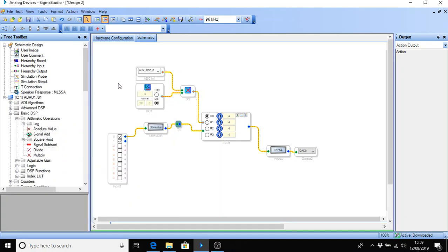So there we are. That's the end of this video on programming filters. There are other methods of selection, as I said. Instead, you can use a binary input on here by having 4 of these and using these as general purpose input pins. There's loads of examples from the Analog Devices website as to how to do different things, different interfaces, different inputs and outputs, but this hopefully gives you a bit of an overview into what can be done. And obviously you can cascade these filters and so on and so forth.